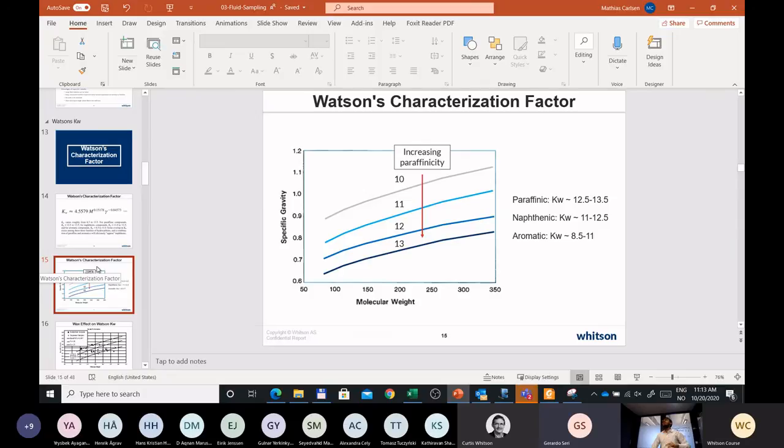Yeah, that's a very good question, and that's always a challenge when you're developing equation of state models. I don't know how many people here are aware of TBP distillation data, but we will go through it in more detail when we go through the compositions and lab PVT measurements. TBP data is kind of ideal data that we would like to have to characterize the fluid, to come up with this gravity-molecular weight correlation.